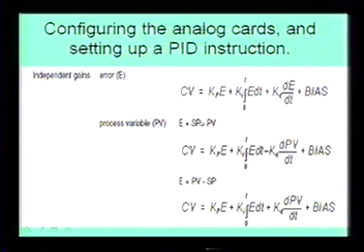So again, if I say I have a P controller, all I have is a proportional controller. What I've done is I've set the Ki and the Kd to 0, or very, very close to 0. So if I put Ki to 0, anything times 0 is 0. If I put Kd to 0, anything times Kd, or 0, is 0. So taking the derivative of the error times 0 is still 0. Taking the integral of the error times 0 is still 0, and you're left with your Kp times your error.